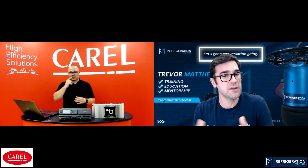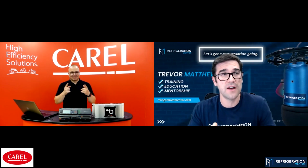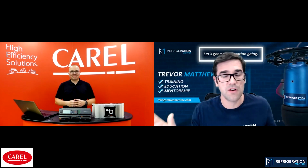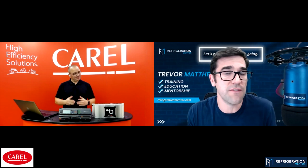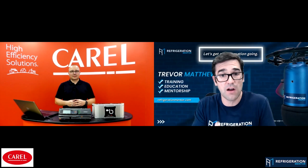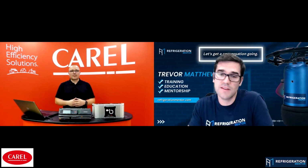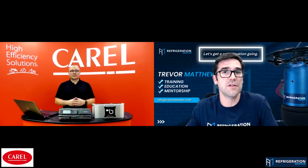Because when you shut down a rack, you don't want to shut down a CO2 rack unless you know what you're doing, right? Because if you shut it down in the middle of the summertime, it's 110 or 40 Celsius out, you could pop off or blow the reliefs or open a relief up. So you want to be aware of that when you're shutting down a whole system, because it does take time to start it back up. It could take 5 minutes, 10, 15, depending on the system. Could take 20 minutes to start your controller back up.